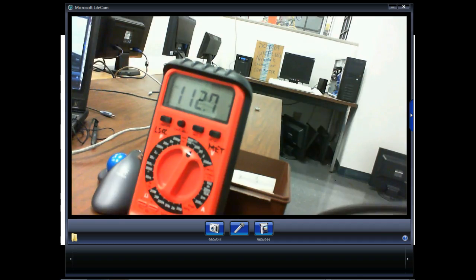So what you're doing when you put it on DC, it's giving you the DC average of a cycle. So I'll have a positive 0.637, a negative 0.637. You average those two together, and you get what? 0. So the average DC value of a cycle is what? 0. Would it kill me?